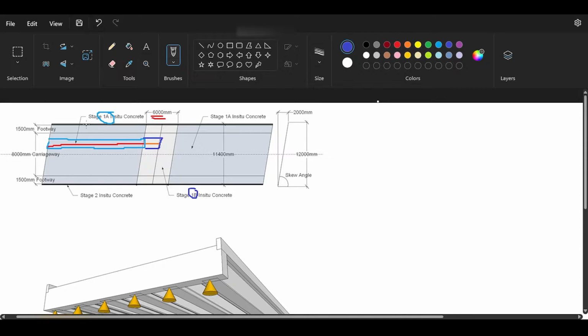So we have the beam, we have stage 1A, stage 1B, and then finally, we have the second stage, which comprises the entire bridge, which is the finalization here. This is the side rail or the barrier, and of course, I don't need to stage them span by span because I will make the entire span with the same stage. So I need to keep this in mind when I define my sections, because I need to explain to the program that each individual piece of the section is part of a design and analysis and implementation stage. So let's keep this in mind.